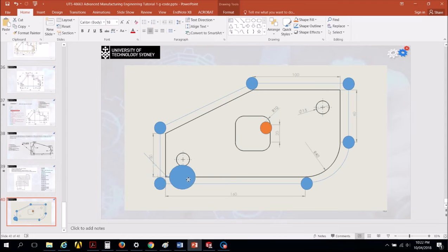So I'll travel with this one till the end of the work part, go up, redo the cutting, go up, do the cutting, up, do the cutting, and continue doing that until you remove the whole unwanted surface.